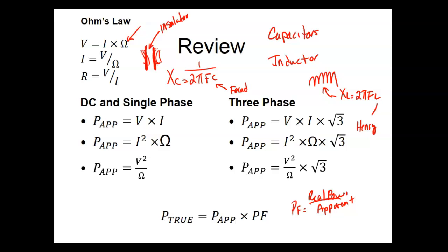So every once in a while, you ever notice you're driving, you see a power pole up there and it's 3-phase and they'll have these 3 little cans up there? Well, all they are is just capacitors. It's in there to do what? Try to bring the power factor back to 1. All the substations have a dynamic power factor correction. So what happens, it automatically shifts around and changes the capacitance in the circuit to correct for that. Your house is corrected for it, so you notice when you get your power bill, it's kilowatts. So the power factor at your house is taken into consideration.